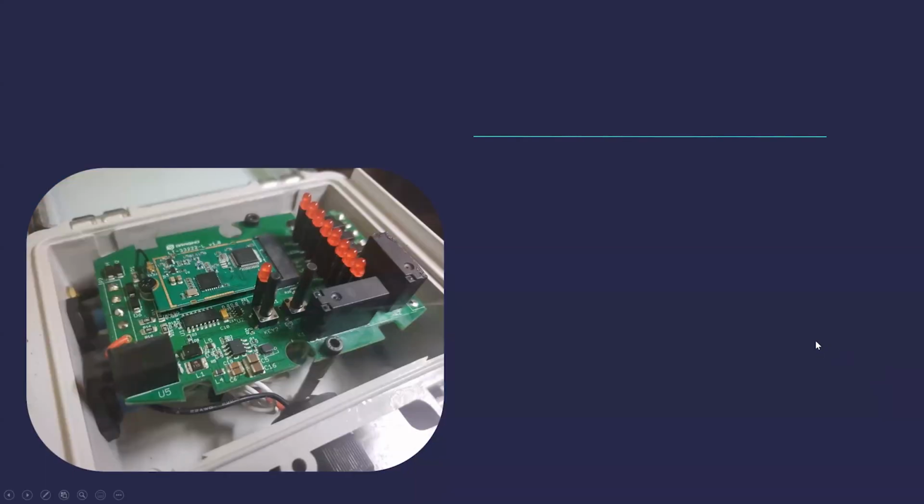This is another Dragino unit. This is an industrial controller, and you can see it has relays on the right. It also has a 4-20 milliamp input on it. It has digital, 0 to 5 volts, 0 to 10 volts. So if you're doing industrial-type applications, it's definitely a viable device to explore.